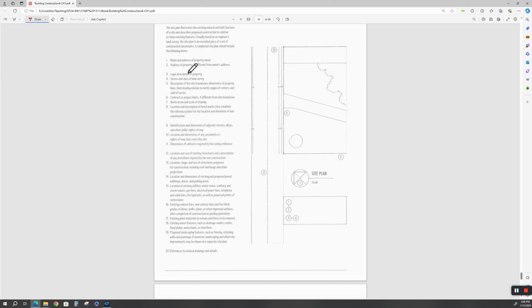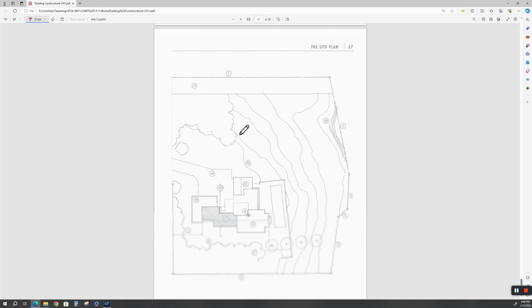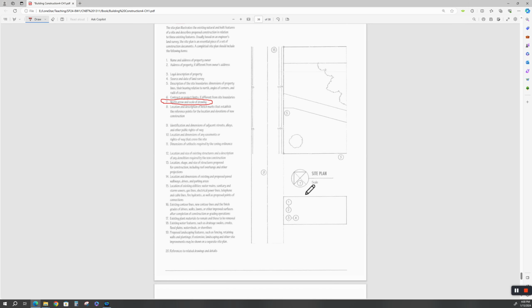So you read down through all of here. It needs to have the north arrow. Oh man, that's my biggest pet peeve. Somebody gives me a drawing for a site plan and that building's not located. There's no north arrow. Oh, that drives me crazy. Here's your north arrow up here. Okay. And the scale. We'll want a scale. And here's your note block. Here's topo lines. Looky here.